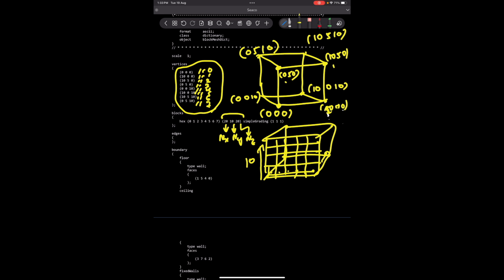These are the things with the help of which you can make a mesh finer or coarser. Finer means you have to give a much larger value, coarser means you can give a smaller value. I'll show you the tutorial also, don't worry about that. Practically we will do it in OpenFOAM, and then I'll show you how it is increasing or decreasing. But first it is required to explain the whole blockMeshDict file.